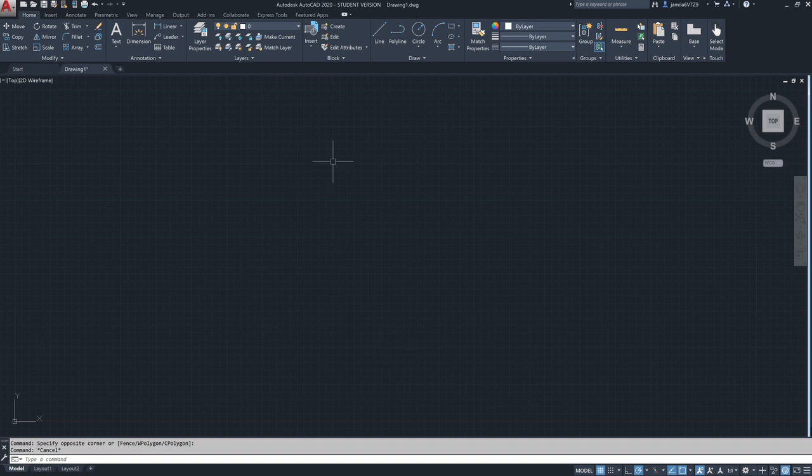They are really useful when you have a lot of projects using the same settings or units or drawing limits. Let's say in your country, people use architectural units. You can set that in your drawing, save that as a template, and reuse that particular template for all new projects. So let's go and change the units for this drawing.